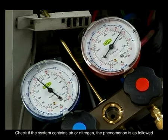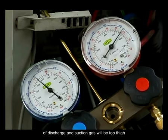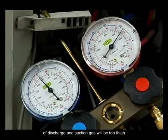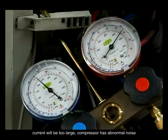Check if the system contains air or nitrogen. The phenomenon is as followed. When it is running, pressure and temperature of discharge and suction gas will be too high. Current will be too large. Compressor has abnormal noise, and the pointer of pressure gauge will be shaken.